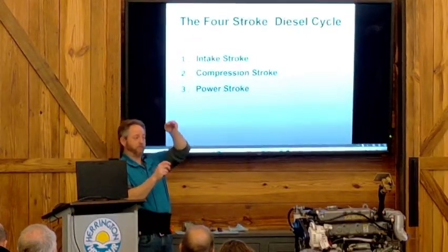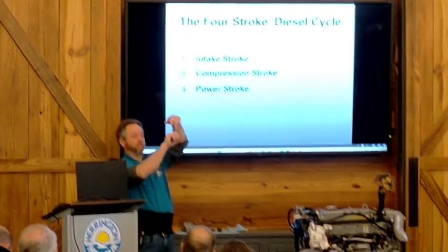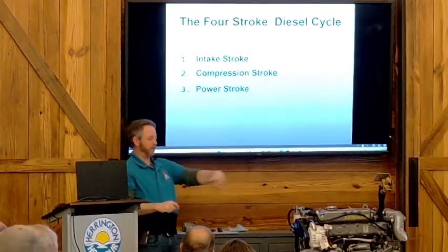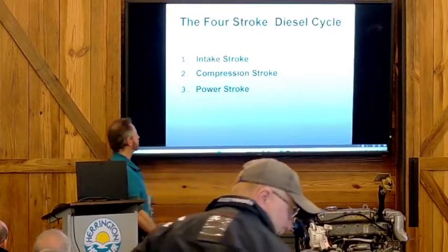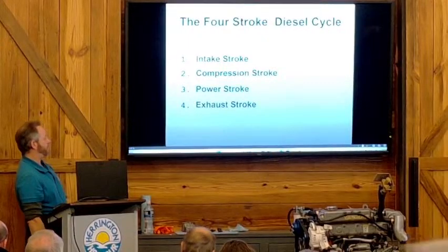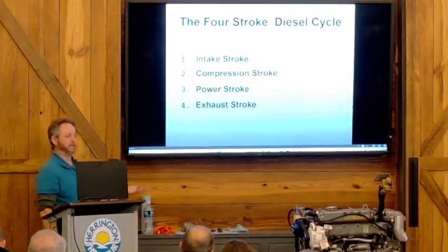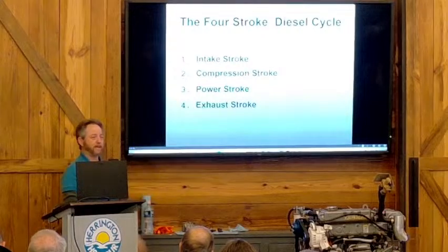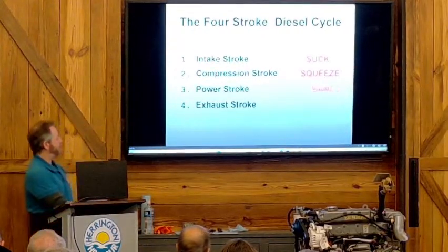The exhaust valve pushes open, piston comes up, pushes all the exhaust smoke into the exhaust manifold and out the engine. So intake, compression, power, exhaust. Now every diesel course ever taught is going to tell you 4 words to remember this by, and that is suck, squeeze, bang, and blow.